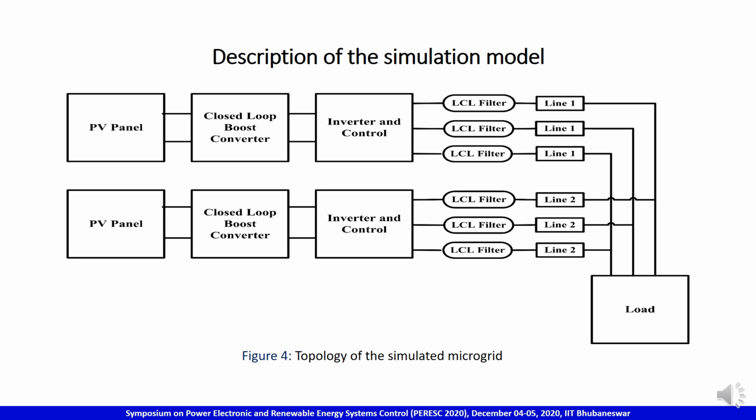The controllers give a voltage reference to a pulse width generator, which controls the inverter's switching. The LCL filter is used at the output of the inverter to obtain a nice sinusoidal voltage and current waveform before the transmission line brings the power to the load.